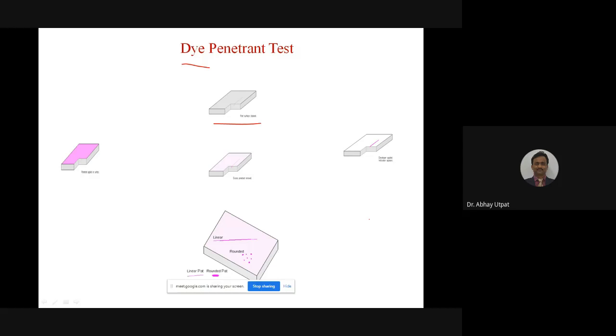And you can do the experiment. If there is a leakage in your pen, you put chalk near it, so that chalk absorbs the ink. Same way, this developer absorbs the ink from the crack. And the picture will be like this: white blanket and red spots. White blanket and red spot means that is a crack. You have to immediately take the pen and make the marking with the help of a marker. Otherwise, the dye will spread, and you can't judge the severity of the crack.